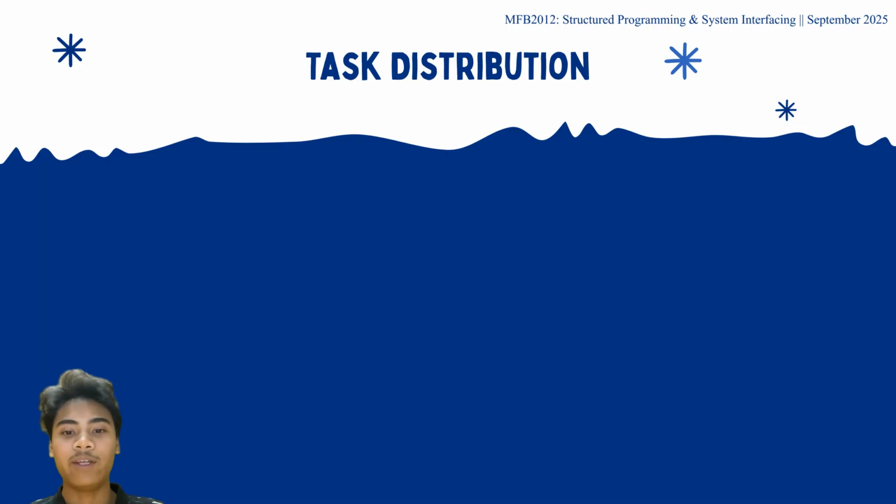Our third member, Vinoshini, is in charge of the soil moisture control. This system displays the soil moisture level and will activate the water pump for 5 seconds in 10-second intervals if the soil is dry. Lastly, Kendrick is in charge of the temperature control system. If the temperature is higher than the optimal temperature, the fan will activate to reduce the temperature.